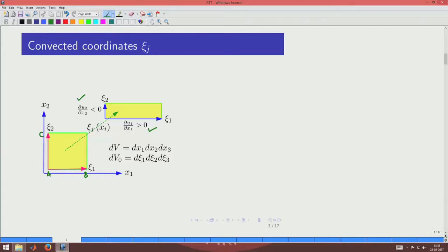Now, what we are doing is that we want to define the volume of the fluid element using the spatial coordinates x1, x2, x3 like this. Because the spatial coordinates we are always taking as orthogonal, we can take it as a triple product of dx1, dx2, dx3 along the unit vectors, and we can already see that the product directly gives us the volume of a volume element in the spatial coordinates.